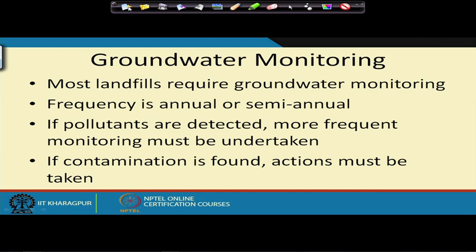So that may cause it. Since it is caused by the landfill, many times the landfills are told that you need to clean it up, although it has nothing to do with the leachate or the municipal solid waste. It is just to do with the changes in the hydrogeology condition of the site, which happened because of the liner system. And so then it becomes the landfill's liability to clean it up, to come up with a system so that the groundwater iron contamination is removed. I'm just giving you one example, but there could be other examples where things under reducing conditions become more mobile, travel and contaminate the groundwater.